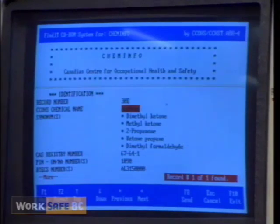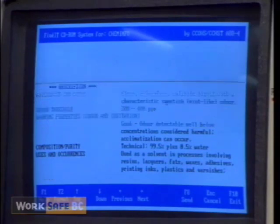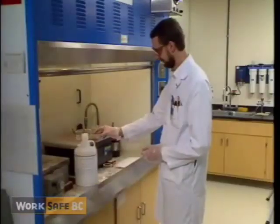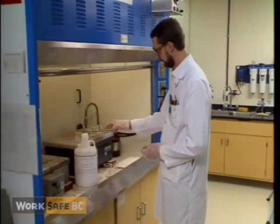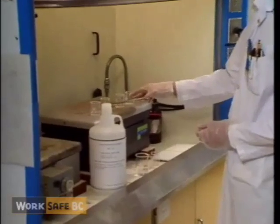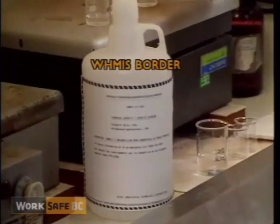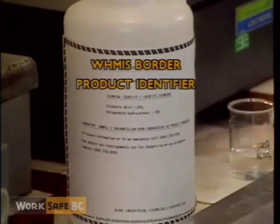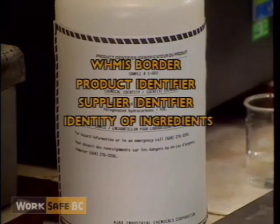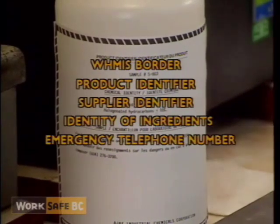Suppliers of such chemicals are required to provide an MSDS, except where the label discloses all the information required on the MSDS. Supplier labels for laboratory samples packaged in less than 10 kilogram quantities and for which no MSDS is available must display the distinctive WHMIS label border and disclose the product identifier, supplier identifier, the identity of ingredients when they are known, and an emergency telephone number.